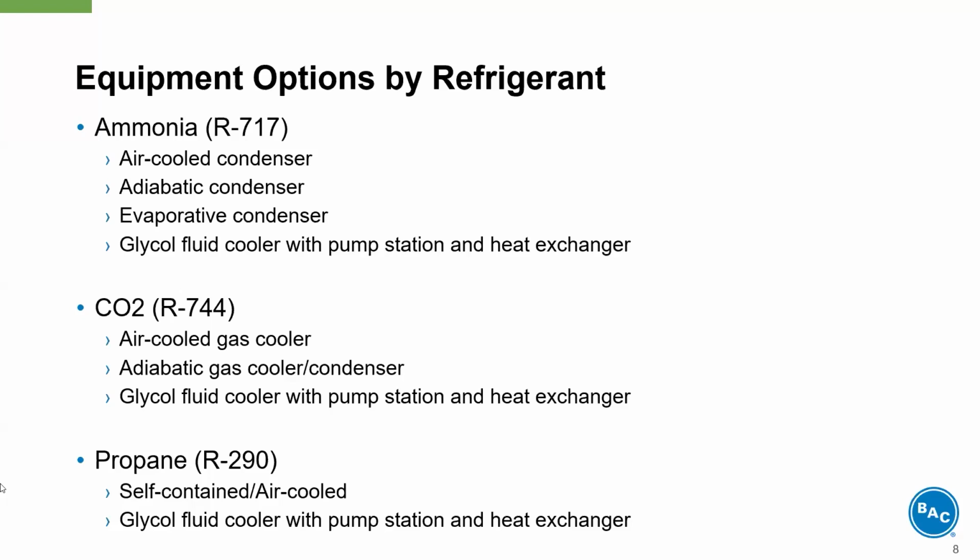But of course, there are the options that are water cooled. So we'd have that, again, that water glycol loop with a pump station and individual heat exchangers for each case or for each rack.